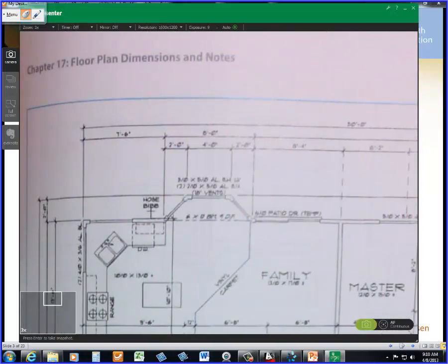So there's a little gap always placed, and if there's some kind of round feature, CAD is notorious for when we select something round on a corner, the extension line kind of blends into the radius for some reason, because your connection point might be way down at the tangent.